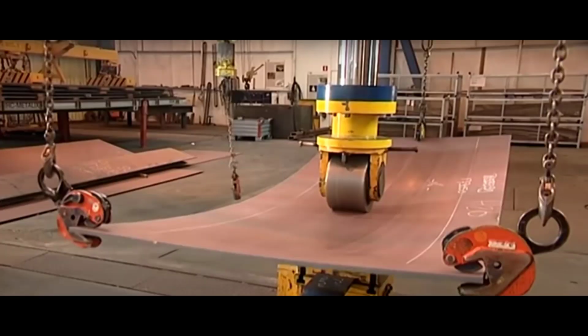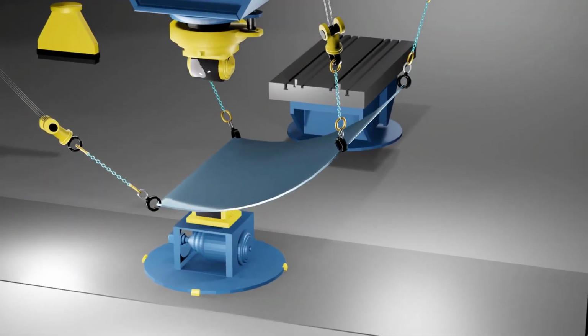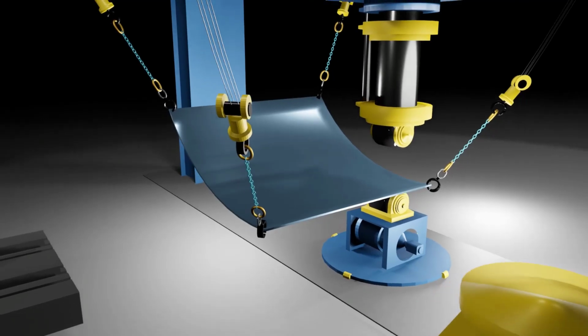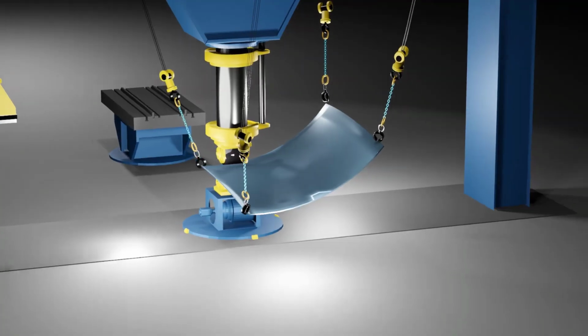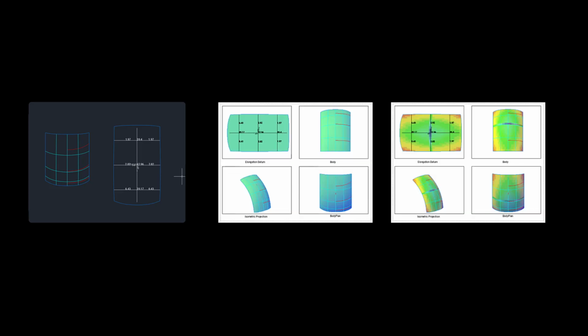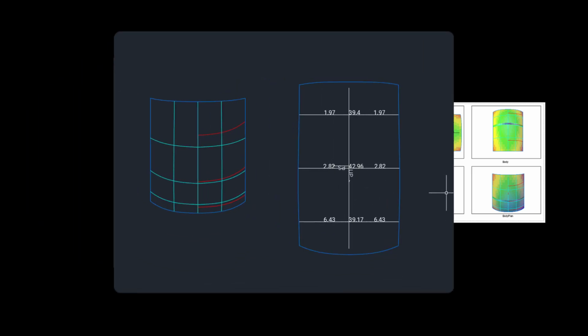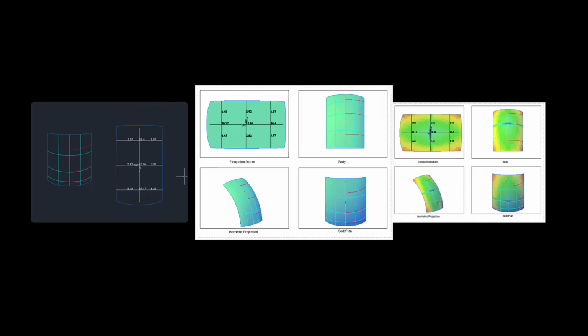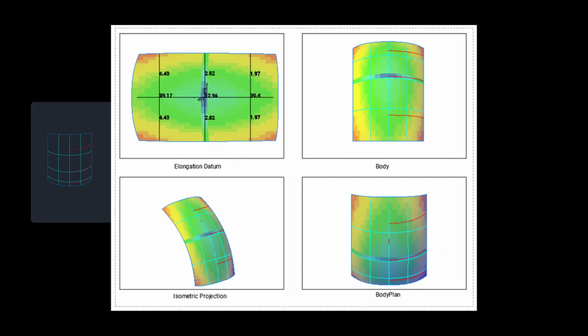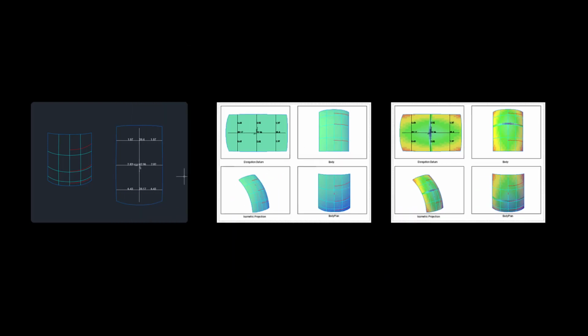As the goal of generating elongation information is to provide the press operator with the necessary reference values and information to create appropriate plate shapes, the final step is to generate output files that can be used on the production floor. Currently, there are three options for viewing the elongation information for production. A, having the markline and elongation values etched to the plate itself for reference. B, generating a PDF containing just the values and marklines. Or C, generating a PDF displaying the strain map along with the elongation datum and information.